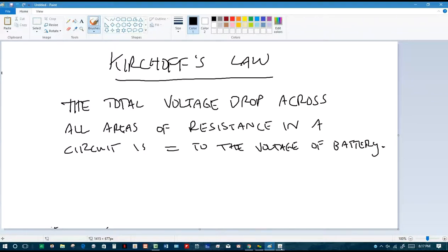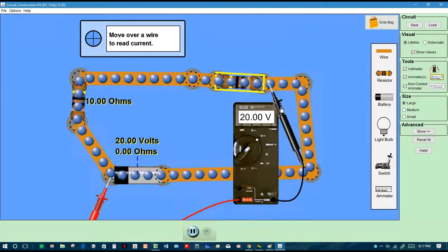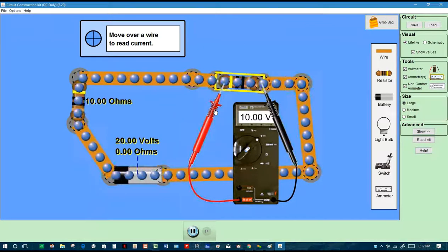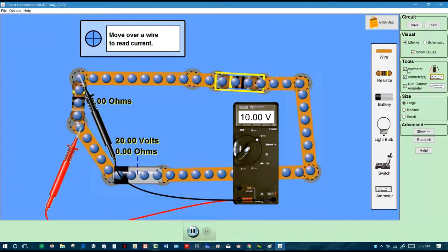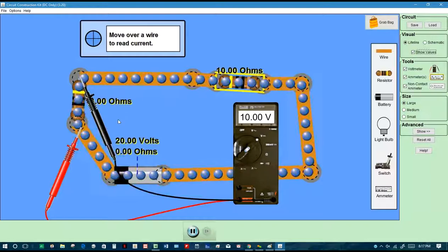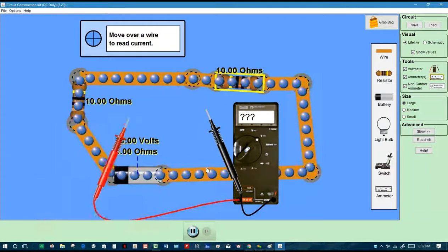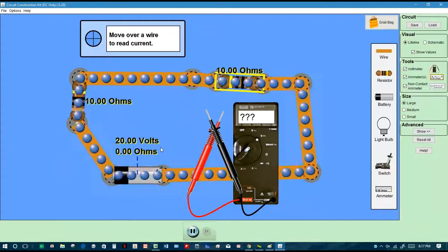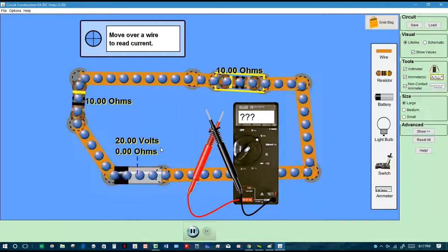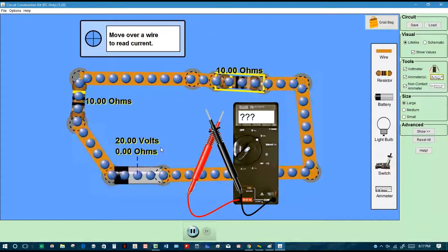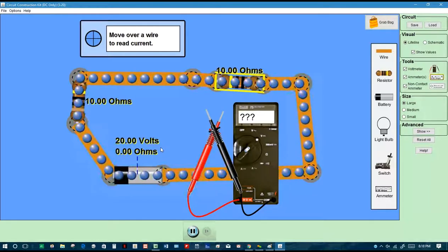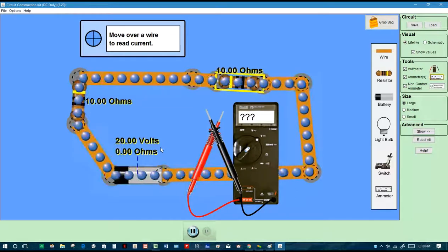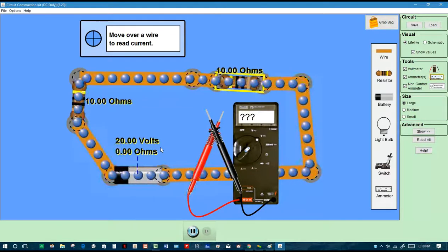Okay. It happens to be that it was an equal 10 volts, a voltage drop of 10 volts here, equal to this amount over here, only for one particular reason. Because if I bring up these values again, what are the values of those resistances when you compare them? The resistances themselves of the resistors are both 10 ohms, right? Yeah. And so it's using equivalent voltage because it's equally difficult to get through the first resistor as it is to get through the next resistor.